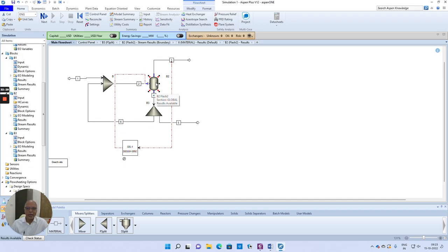As long as you don't change the temperature and pressure at which the flash column is operating, that temperature and pressure is going to dictate the composition of the vapor product and bottom product. You can verify that from your VLE information. So until and unless I change this temperature or pressure or some conditions at which the flash column is operating, I will not be able to bring in any change in the composition. Right now, the recycling of either the bottom product or vapor product is not influencing the temperature and pressure at which the flash column is operating, so the compositions will remain the same.